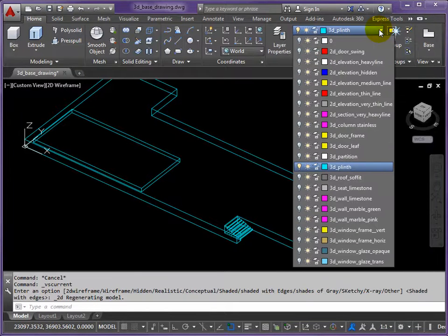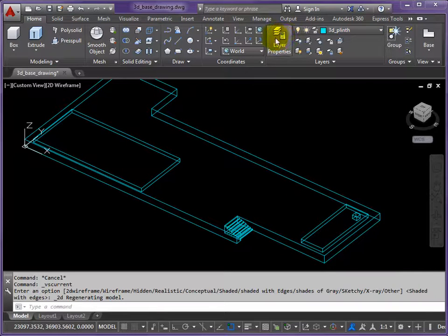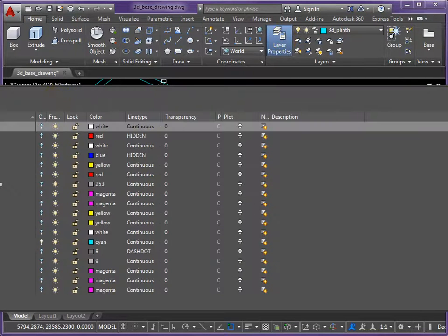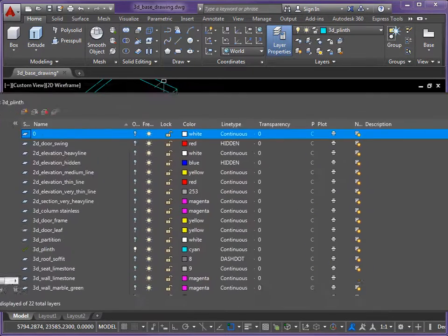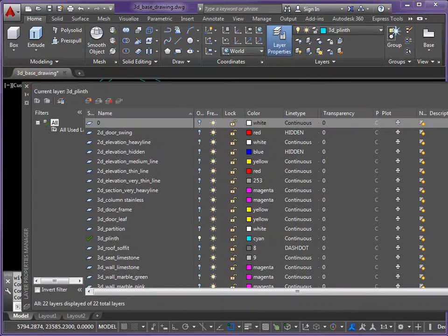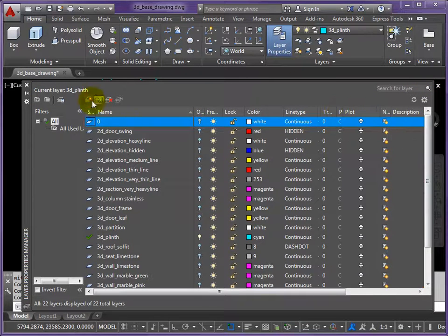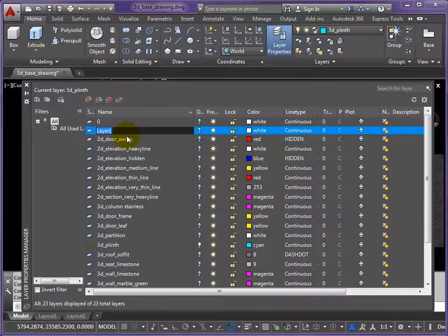I don't think we've got a water layer, so we'll need to make that one. So use the full layer dialog for that. Let's just bring this in so I can read it. I'll keep it tucked in so I can see it from now on. Okay, and we want a new current layer. So this will be 3D water.